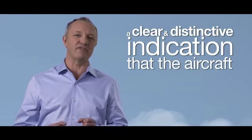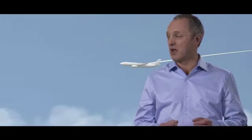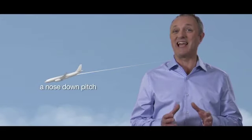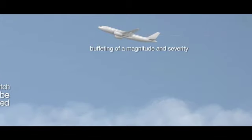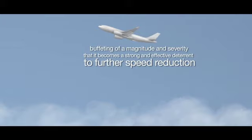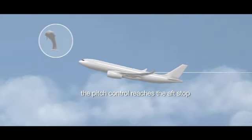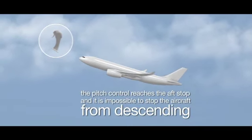The aircraft is considered stalled when the behavior of the aircraft gives the pilot a clear and distinctive indication that the aircraft is stalled. Indications of a stall, occurring either individually or in a combination, are a nose-down pitch that cannot be readily arrested, buffeting of a magnitude and severity that it becomes a strong and effective deterrent to further speed reduction, or the pitch control reaching the aft stop, with it being impossible to stop the aircraft from descending.